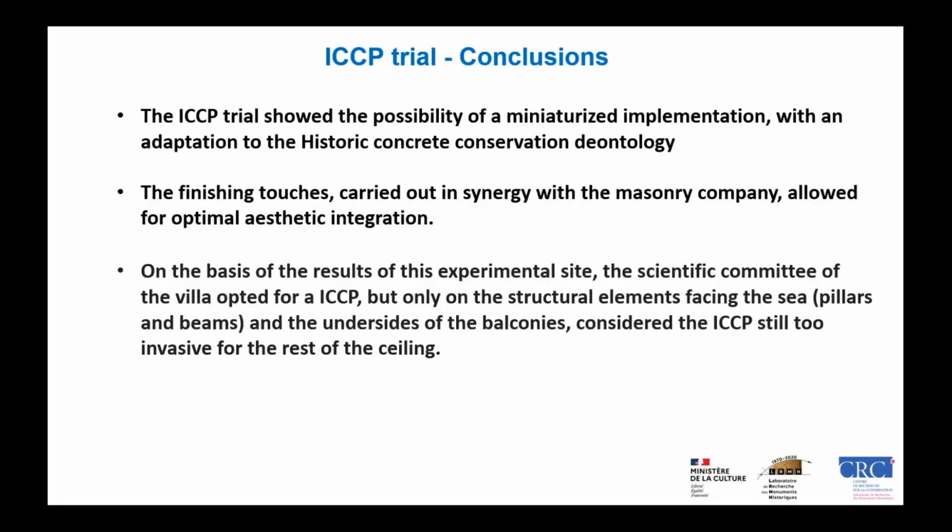And the conclusion of the trials is that it was possible to miniaturize the implementation with an adaptation of the historic concrete conservation deontology. There were nevertheless some finishing issues, and it was a success to have a synergy between the masonry company and the ICCP company. And on the basis of the results of this experimentation, the scientific committee of the villa opted